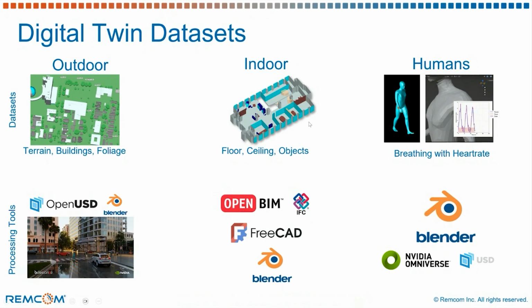Digitization of indoor floor spaces is another area of growth, where we have over-the-air wireless testing performed in very complex indoor environments representing customer use cases, namely apartments, houses, offices, factories, etc., where physical testing becomes extremely challenging. And we have digitized real spaces using LiDAR, using scans, and using the ability to import and create floor plans by hand.